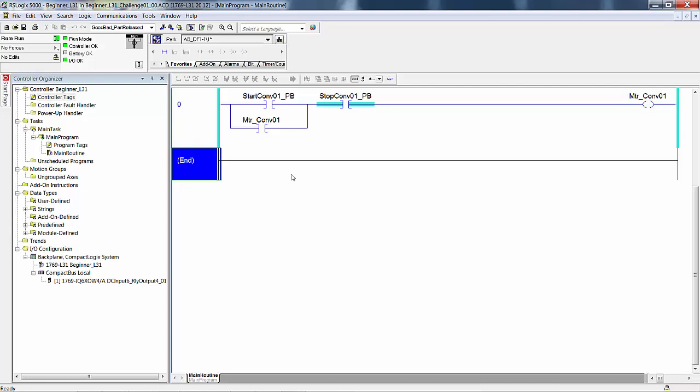If you do not understand this logic, a true if on instruction examining the bit in memory whose state is controlled by a normally closed stop push button, then you need to revisit the earlier video lectures on Introduction to PLCs.